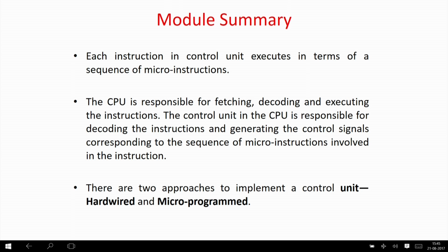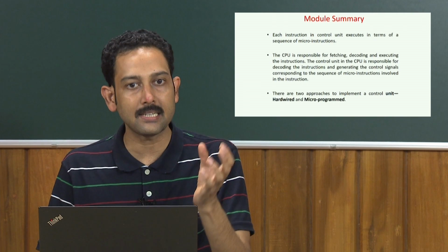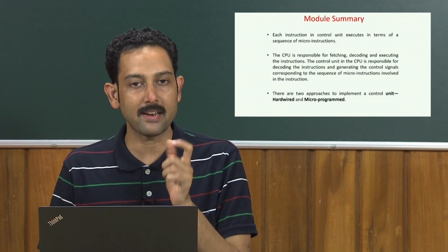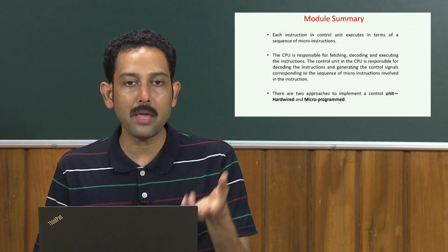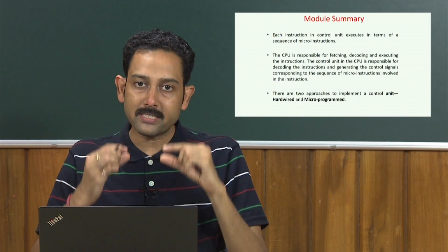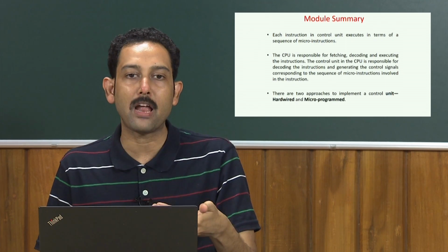That will involve some micro operations or micro instructions. First you have to give the address 3030 to the memory address register. Then you have to wait for a certain amount of time until the memory generates a signal that the data from 3030 has been given to the memory buffer register. That is a control signal which has to be read from the memory. Now your instruction register or your accumulator will read the data from the memory buffer register.